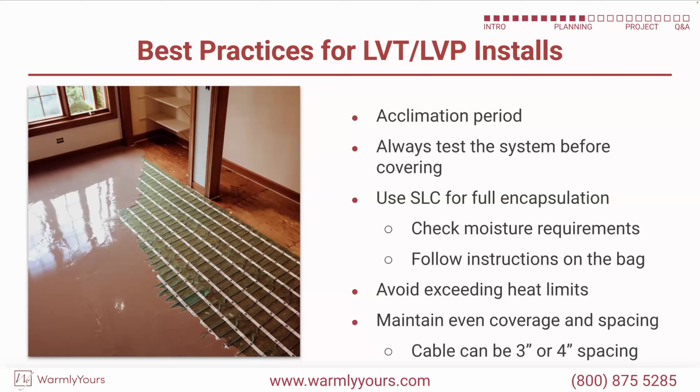Also, the splice between the non-heating lead and the heating wire needs to be encapsulated in thin set or self-leveling cement. Now, if you notice, we don't say thin set in this. Thin set is not acceptable. And I personally have visited a couple of floors where they tried to do a couple things.